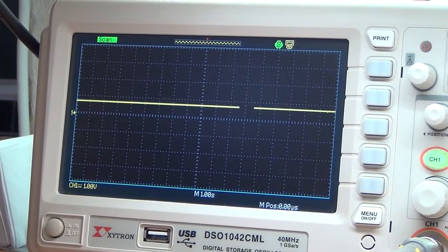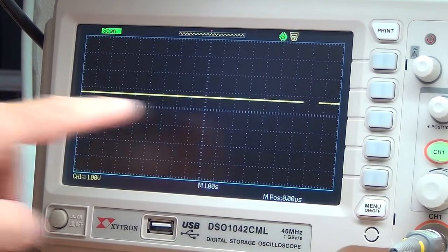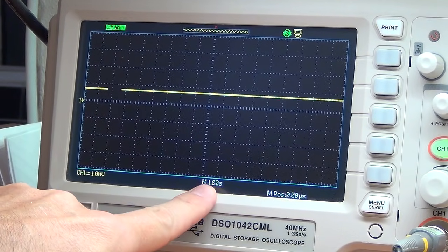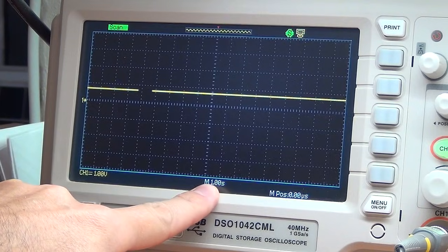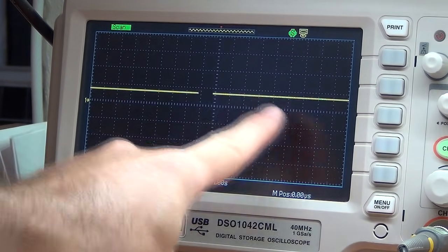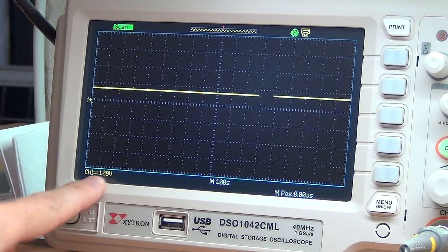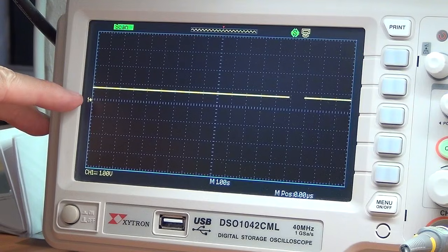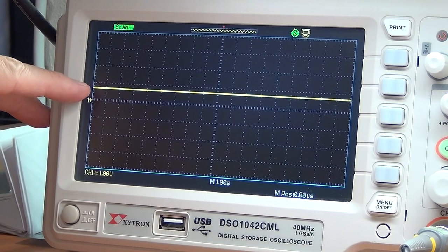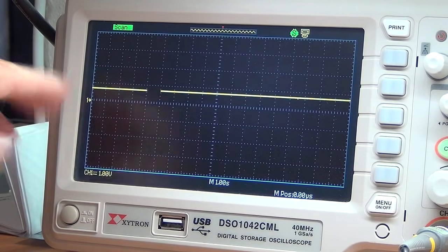Now the oscilloscope is in a kind of scan mode. It's not being triggered by a high frequency signal coming in. I've got my time base set to 1 second per division, so I can show quite a few seconds. You can actually see the scan going across, how slowly it goes across, and I've got it set to 1 volt per division. So my reference is set at the 0 line. So as you can see, we're just under 1 volt of charge in the capacitor currently.